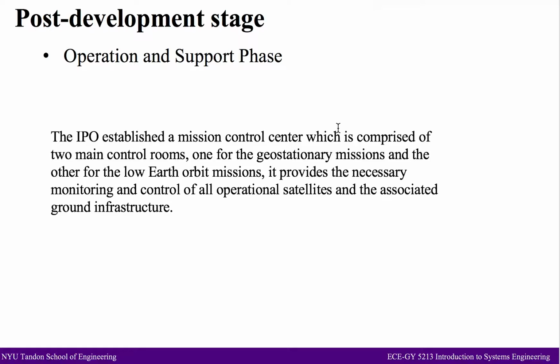The endpoint satellite system uses a mission planning system in conjunction with a flight dynamics system to produce a weekly automatic schedule. This schedule is used to send automated procedures to both the spacecraft and the ground facilities, and verification of successful completion of the procedure comes back to the monitoring and controlling system in the spacecraft and the ground facilities.